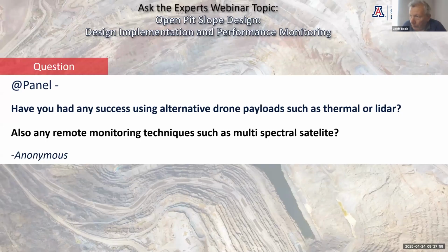And the other thing that I've been seeing a couple of times with drones for mine closure is when you can't access a pit lake because you've had ramp failures upon closure. There's now means to put water sampling equipment on drones and even depth sampling equipment on drones.